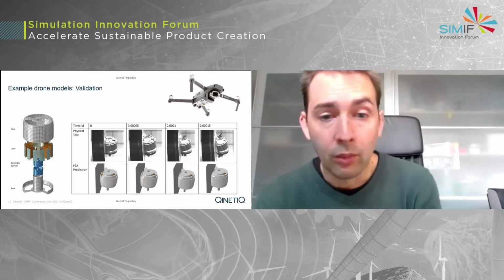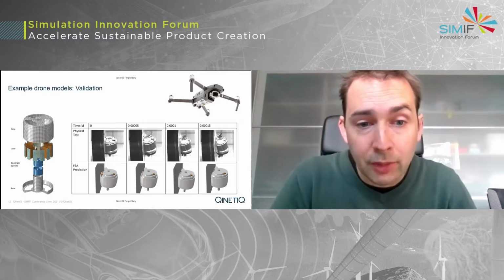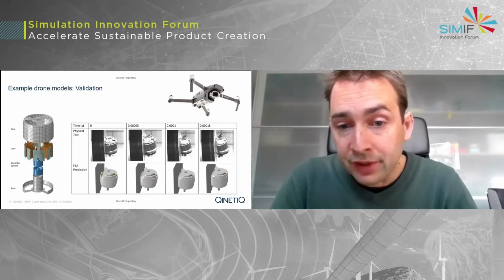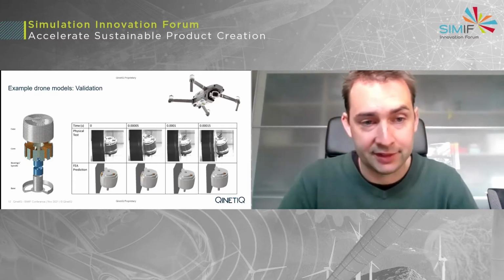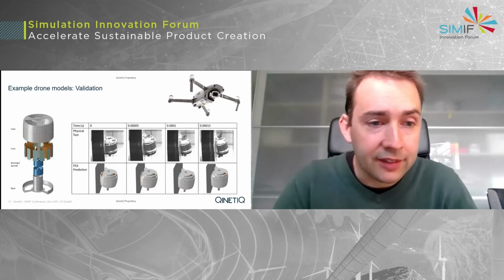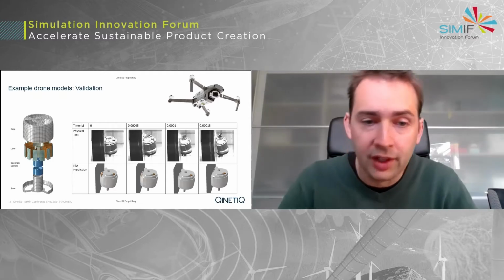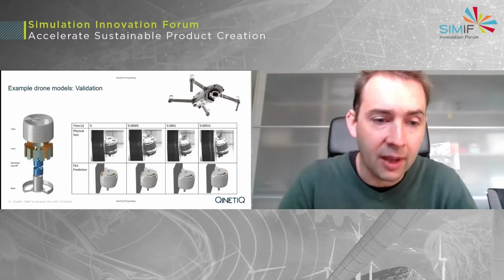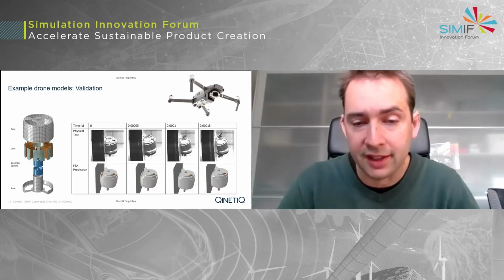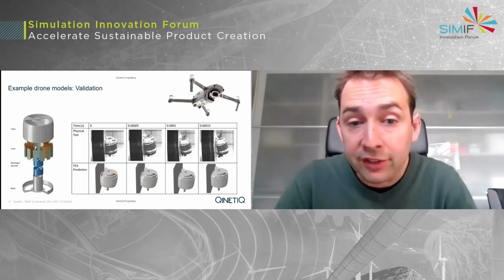So what we do, having generated these models, we do a range of different calibration and validation tests. These typically start out with some static crush tests with uniaxial machines, where we compare the crush response, the force displacement response of the components against our simulated surrogates.